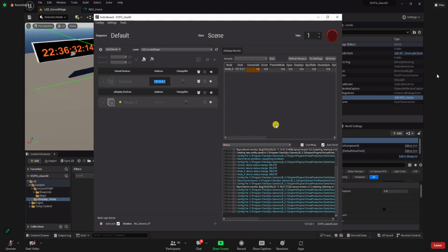And once we add that, it continues to fill out the log, and this is helpful in troubleshooting. Everything that you see in this log should be blue or white. If you're seeing lines that are yellow or red, that is an indication of a problem.